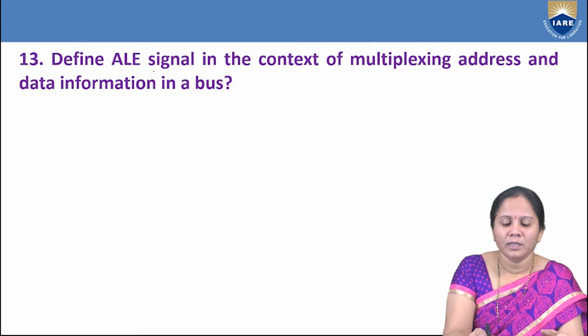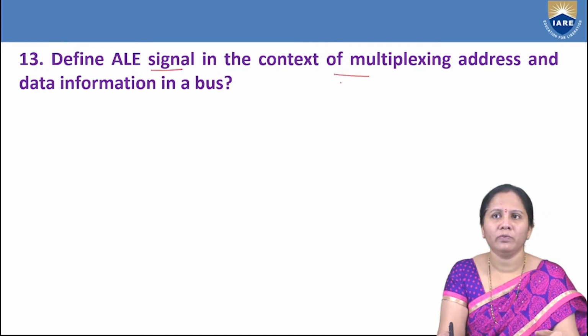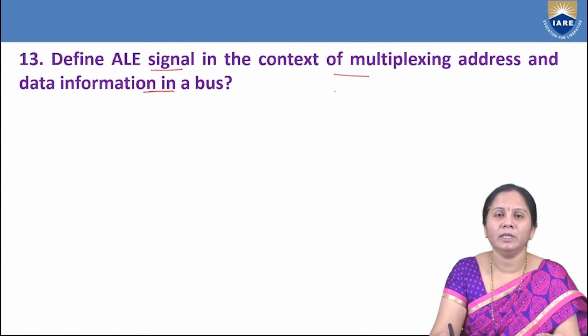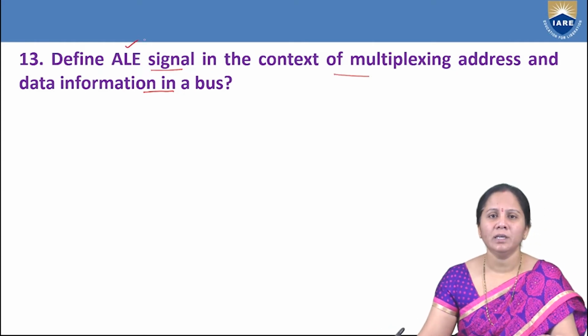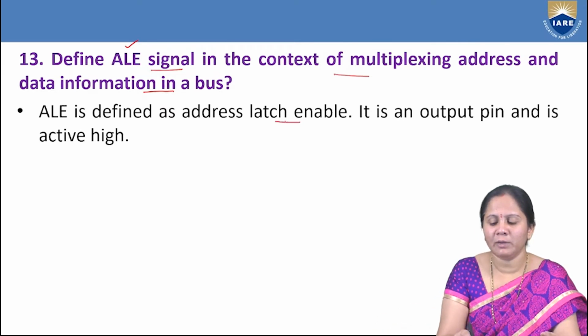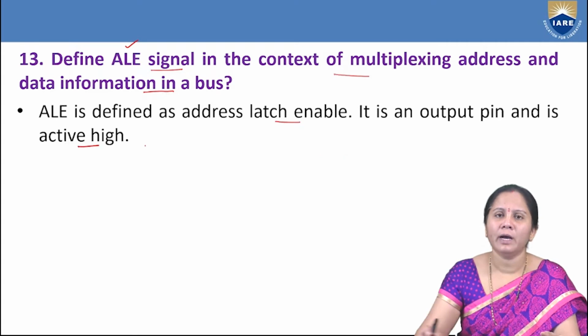And define the ALE signal in the context of multiplexing address and data information in a bus. So what does the ALE signal mean here? ALE stands for address latch enable. Okay. It is an output pin and it is active high.